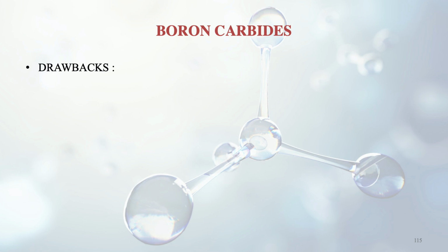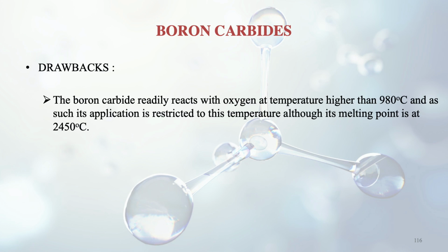The drawback of boron carbide is that it readily reacts with oxygen at a temperature higher than 980 degrees centigrade, and thus its application has to be restricted to this temperature, although its melting point is around 2450 degrees centigrade. And the second drawback is that it is very costly.